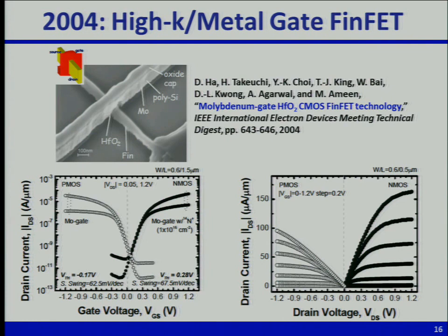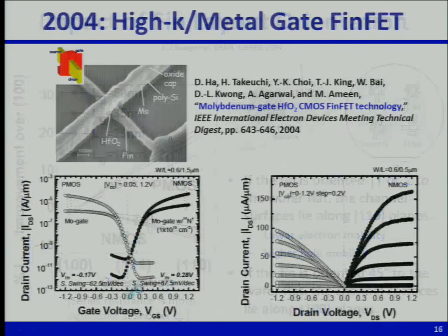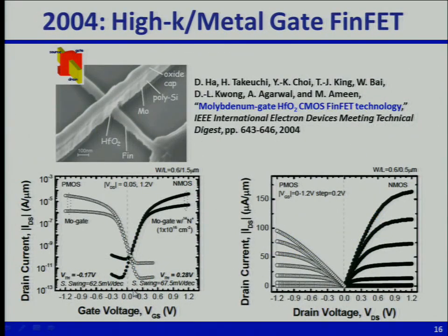And actually, that provides for the best gate control. So basically, if the gate voltage is changing, you're changing the channel potential perfectly. So in principle, you can get 60 millivolts per decade, if the drain capacitance is not significant. In some of these devices, it's pretty close, as you see here, close to 60 millivolts per decade. So if you get a steeper subthreshold swing, as in the homework assignment, was that due already? Okay. You can get a better on-off current ratio.